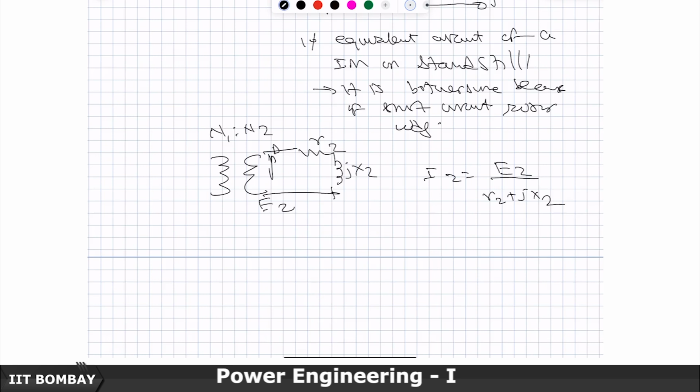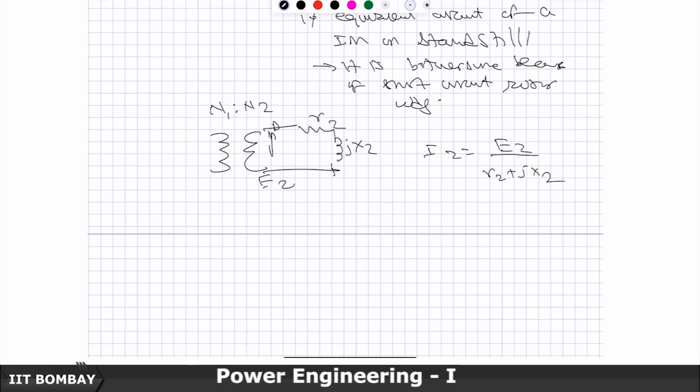This is what is going to cause the large current to flow through this, and when this current flows, a similar thing will flow with a phase displacement of 120 degrees lagging in the B phase winding, and a similar thing will flow with a phase displacement in the C phase winding. So, it will also flow in the C phase with another 120 degree lag from the B phase, and so these 3 currents